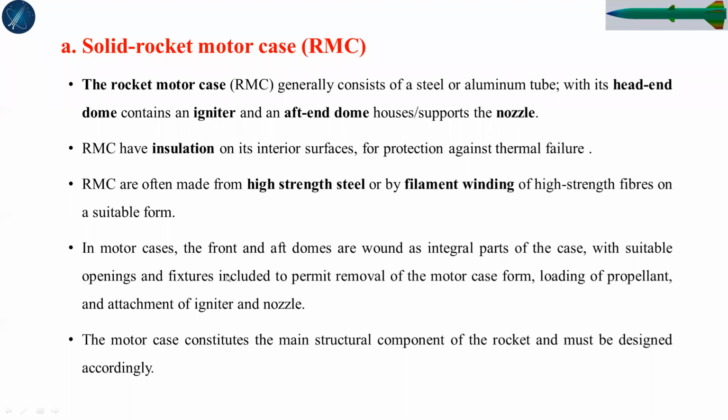When we are manufacturing it, the front dome and the aft end should be integral parts of the casing, with suitable openings and fixtures included to permit the removal of the motor case and loading of propellant and attachment of igniter and nozzle.